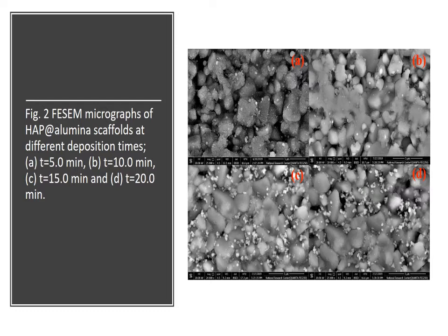For other samples, the latter spheres refer to the aggregated grains of hydroxyapatite, which have dimensions around 0.26 micrometer, reaching around 1 micrometer. The intergrain porosity among grains of alumina tends to be filled with hydroxyapatite, while the surface roughness is reduced considerably.